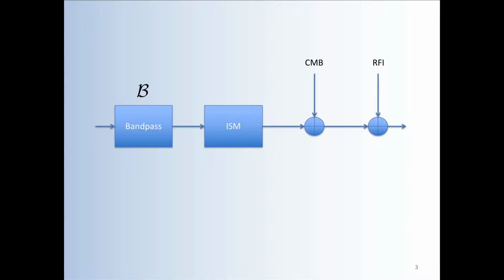We are assuming that the signal is band limited to B, which is the bandwidth, by bandpass or low-pass filter at both the receiver and at the transmitter. This is not a characteristic of the electromagnetic propagation between stars, but rather is an artificial restriction of bandwidth, presumably to constrain the amount of noise that interferes with the signal. So what we're interested in this talk is specifically the relationship between the design choice of bandwidth B and the other parameters of the communication, such as the transmitted power and the reliability and other characteristics.